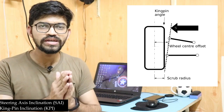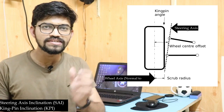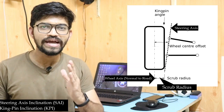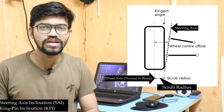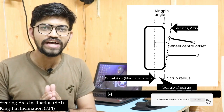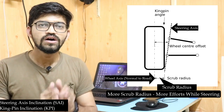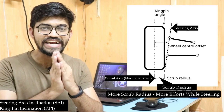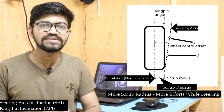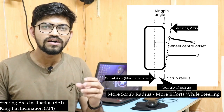Over here, the steering axis is present for both the wheels, and the axis of the wheel is also there. The distance between the axis of the wheel and the steering axis is called the scrub radius. Now if the steering axis is completely vertical and the axis of the wheel is completely vertical, in that case the scrub radius will be more, and while taking turns, the driver has to apply more effort. So to reduce that effort, this steering axis is slightly inclined in such a way that the scrub radius will be less. The lesser the scrub radius, the lesser the effort of the driver while steering the wheel. So this is the reason the